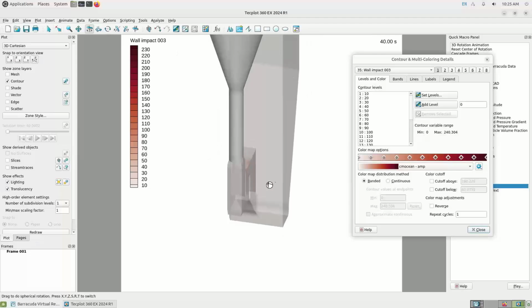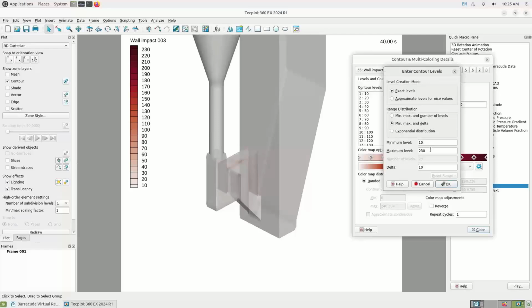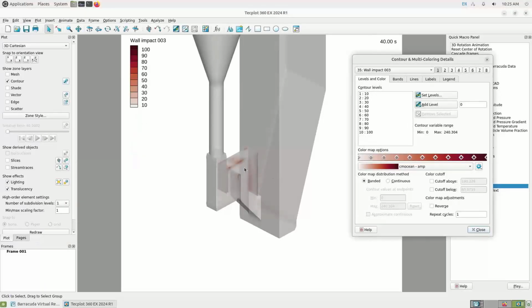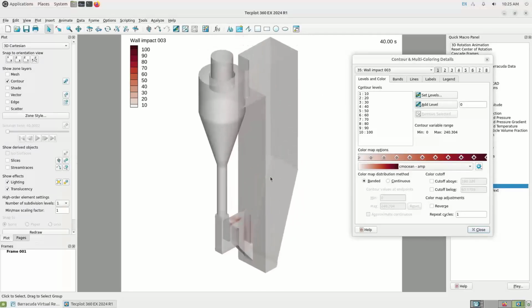And again, adjust the limits so that you start seeing things more clearly than the absolute maximum limits might give you. The nice thing about this is, within Tecplot, you could potentially make 3 frames in this case and show the erosion from each spatial region and have a really nice visualization that's easy to communicate these results to other people.